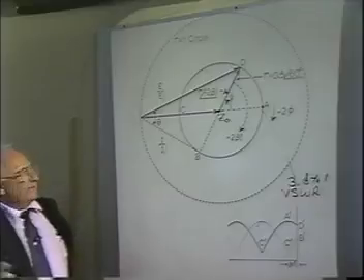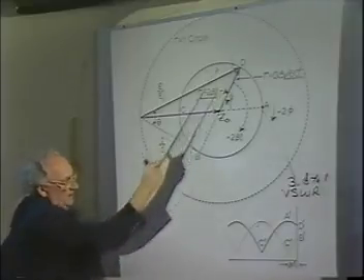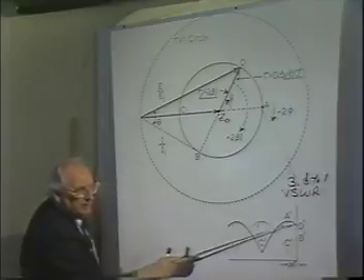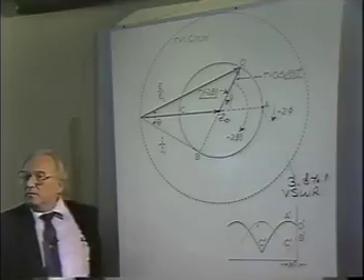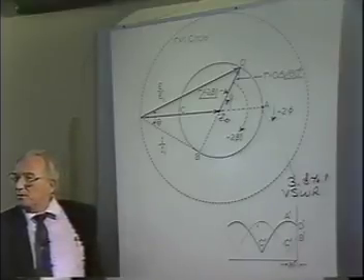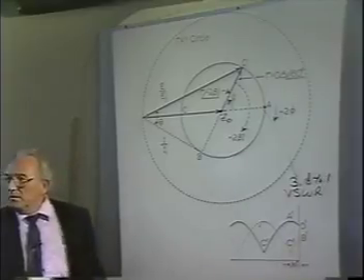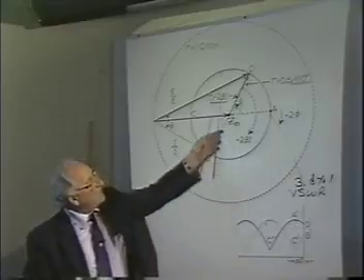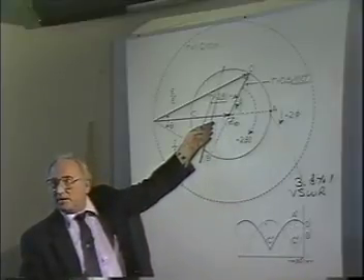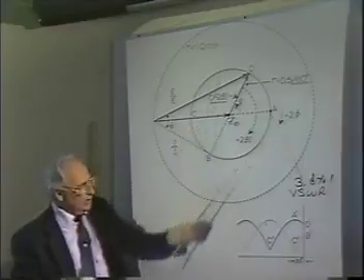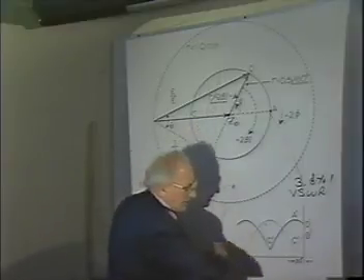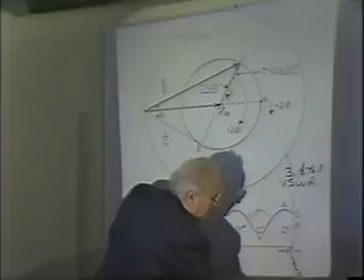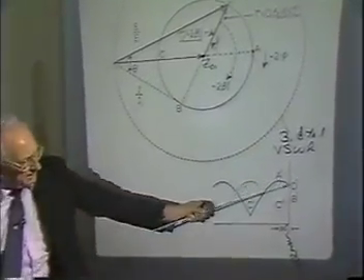Now notice, this point D is the same point as this D prime here on the transmission line. D prime then is an impedance other than a pure resistance, isn't it? In this case, what is the relative value here? D prime. What side is it in? The inductive side of the chart, right? So we know then that this load impedance here is a resistance in series with an inductance right here.